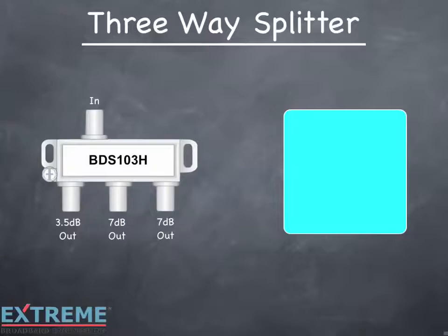On the left is an unbalanced three-way splitter with one leg losing 3.5 dB and the other two losing 7 dB. On the right, let's build the symbol equivalent of the three-way unbalanced splitter. Let's first look at the 3.5 dB leg. If the two-way splitter is the building block and it loses 3.5 dB, we know that this leg is fed directly from one leg of a two-way splitter.